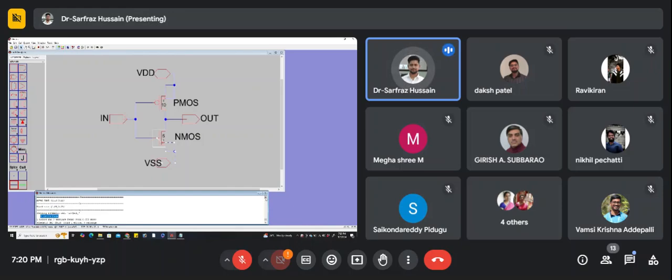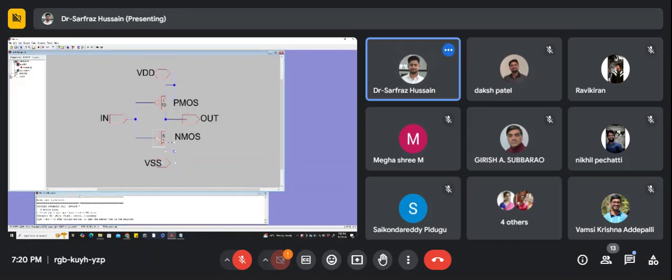So what is that error? You can see that if you go above, where there is an error. If you scroll up, you will find what the error is. The other way you can get the error is to go to the Explorer. Here you will find this error tab. If you expand this one and double click on it, you get to see that the error is somewhere here and it is called an unnecessary pin.